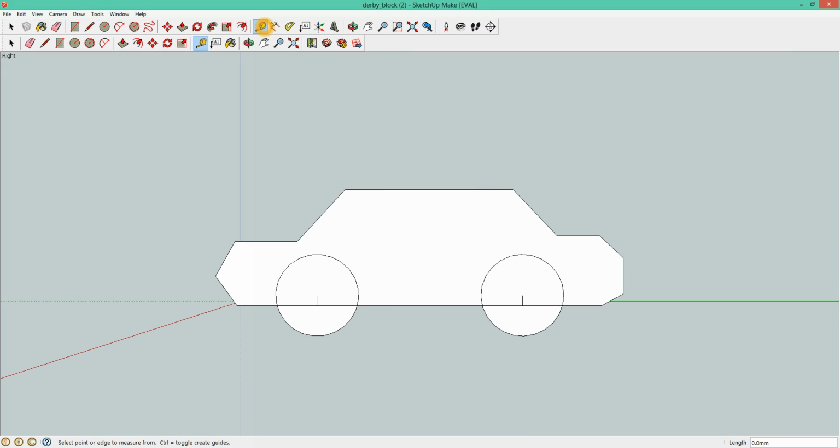Okay, what it asks you to do next is it asks you to go ahead and use the measuring tool. So go ahead and click on the measuring tool, and we're going to make sure that we start right here at the bottom, not in the middle of your line, but right here at the bottom of the car. Okay, we want to click it, and again, we want to measure all the way down to the bottom of this circle. If it keeps on going left and right, that's fine, because again, it is a circle. You want to be at least, again, at least above 7.55. So mine's about 9 millimeters. So again, it tells you here on the screen, as well as it'll tell you down here in this corner. Okay, so it seems like we are okay.